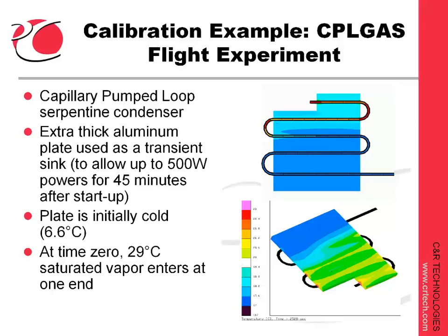We have temperature data at 3 points along this condenser, and we've made a thermal fluid model of the plate. But we could only guess at the bond between the plate and the cold environment since it was a commercial conductive pad. We also don't know how well we can predict the condensation coefficient, since this was actually not plain tubing but a grooved aluminum extrusion. We're not even sure that all the 500 watts that were applied made it into the condenser, or that the 29 C saturation measurement is actually correct.